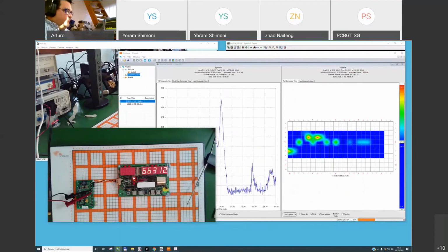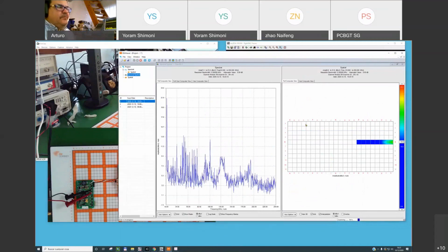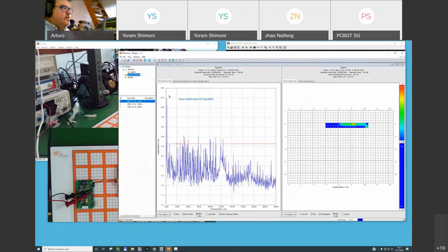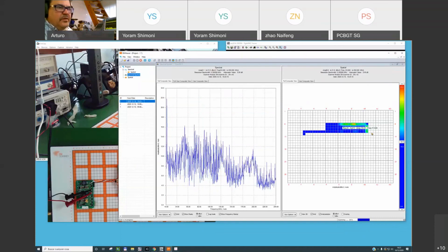So now I am interested in finding where is the origin of the 11 megahertz and where is the origin of the 126, 130 megahertz signal. Okay, reset zoom so we can scan the full number. Look at this area here. The main frequency is 11 megahertz. You can see in the spectral scan that the most important amplitude is coming from the first harmonic of the clock. And in the scanned area, this energy is in this area here. Okay, the other areas here are in blue color. The system is powered on. Okay, looks like 11 megahertz is coming through some trace in the PCB in this area.